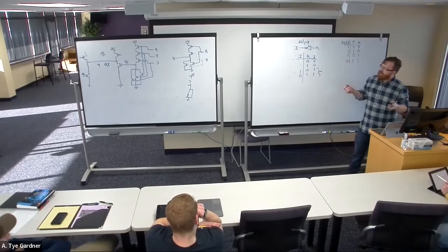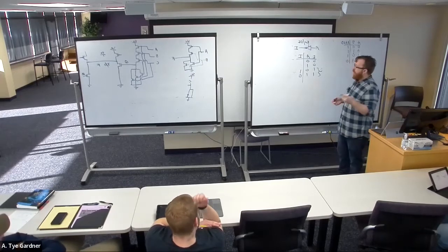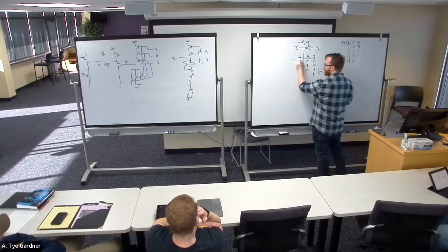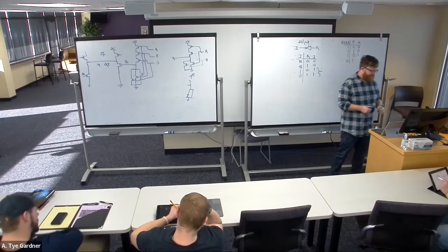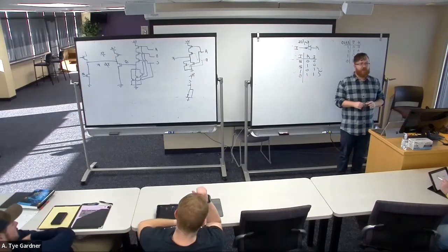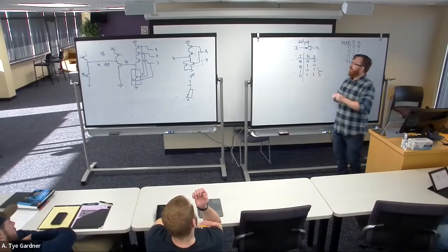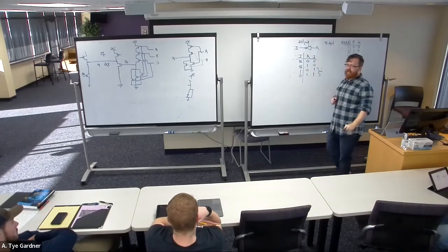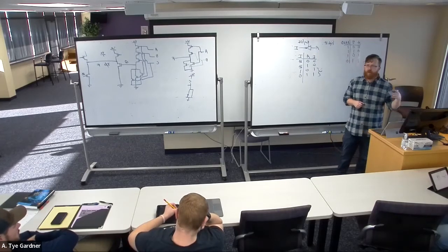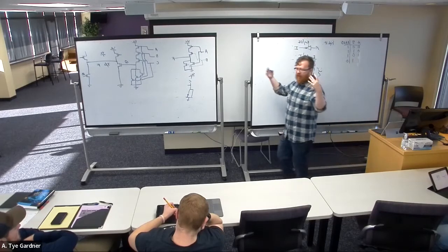Well, there's a reason that I chose I on this one rather than like Z, right? I use Z a lot for outputs. Well, it's because there's Z. Now, Z stands for impedance. And when we write Z, what we really mean is high Z, which means high impedance, which means disconnected, right? If things are not connected together, it's high impedance.